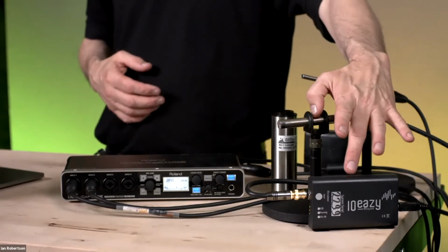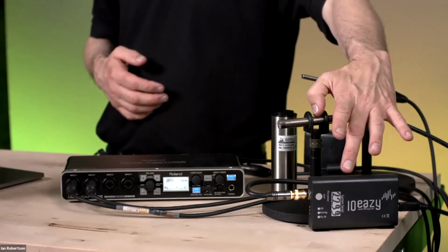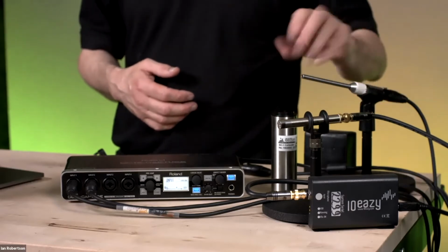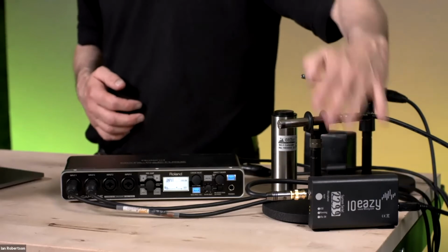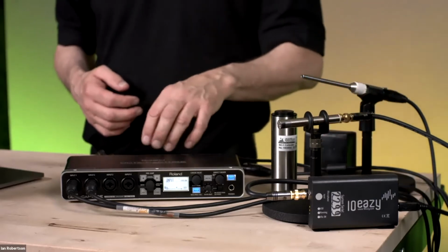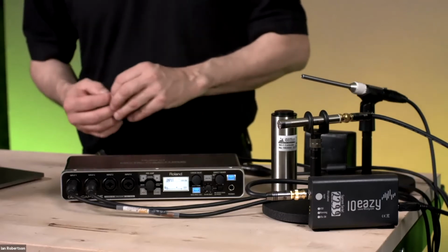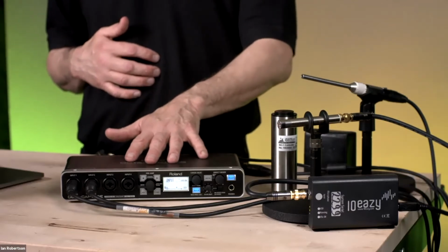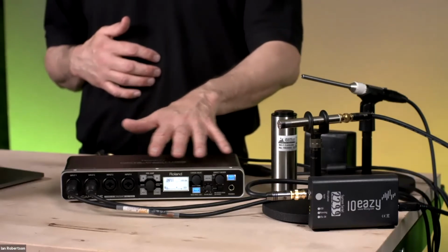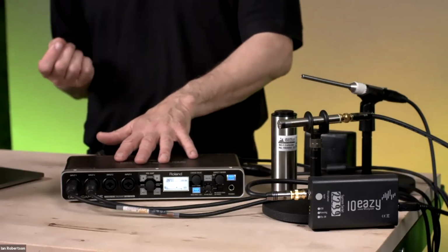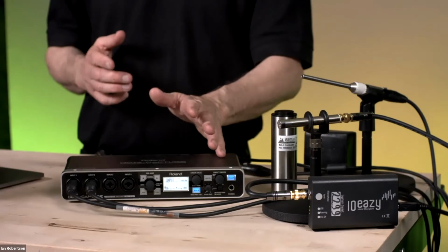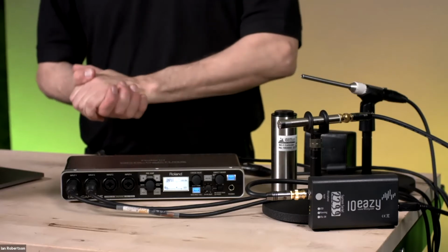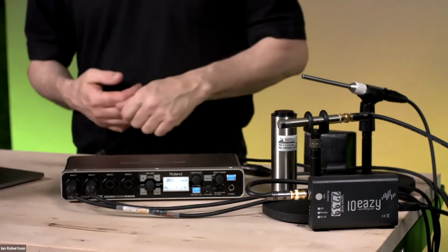This microphone and this interface are calibrated together and locked, so it's a traceable solution, unlike a microphone like this where you can change the calibration and maybe fiddle with the numbers a little bit. So that's what's pertinent about this over a standard microphone. And this is just one of the interfaces that you can use with Smaart. It's one of the more popular ones because it's actually controlled within Smaart, and Smaart is aware of the input sensitivity of the microphone, so you can change the input sensitivity and not throw your calibration off. So if you are doing SPL related things and you want to have calibration, this is one of the better choices to use as an interface.